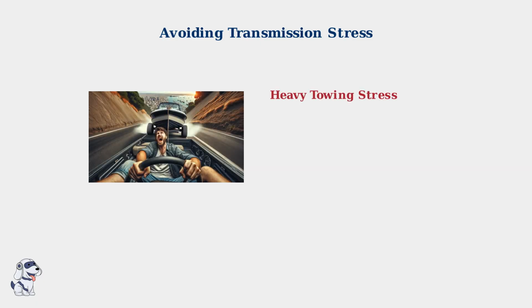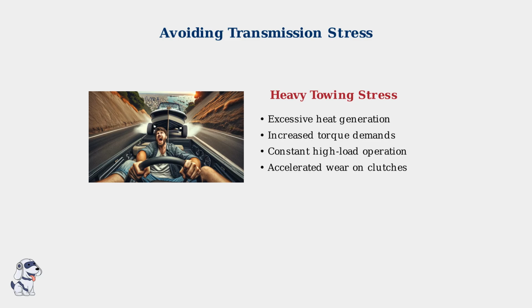Transmission longevity depends heavily on how you treat your vehicle. Avoiding excessive stress through proper driving habits and towing practices can significantly extend your transmission's lifespan. Heavy towing places enormous stress on your transmission. The image shows what can happen when towing exceeds the vehicle's capacity: overheating, excessive wear, and potential failure. Heavy towing generates excessive heat, increases torque demands, forces constant high-load operation, and accelerates wear on internal clutches and bands.